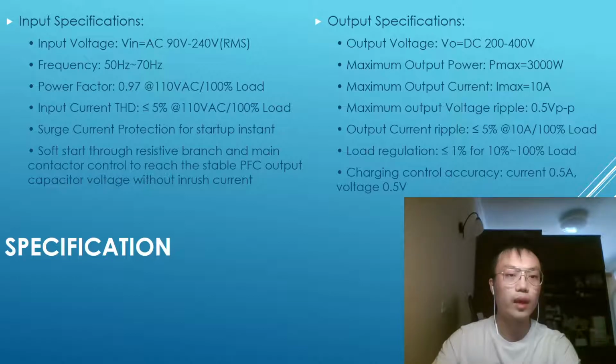And the third, we have surge current protection for startup instant. Soft start through resistive branch and main contactor control to reach the stable PFC output capacitor voltage without inrush current.